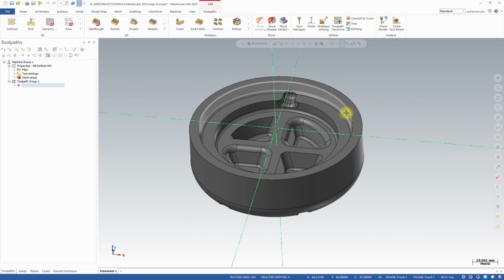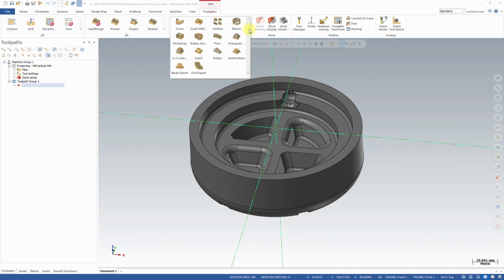Another thing that I wanted to show you is what CNC Software changed in our multi-axis gallery, and this is the most often used section in our tutorials. In this release of Mastercam we won't have morph, parallel, along curve or project curve as standalone toolpaths. They are all combined in unified.